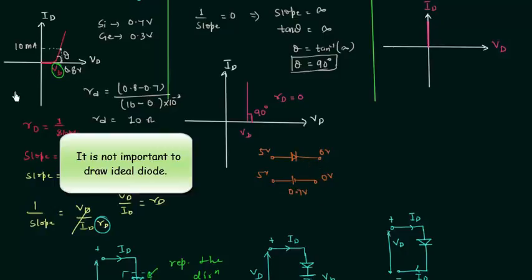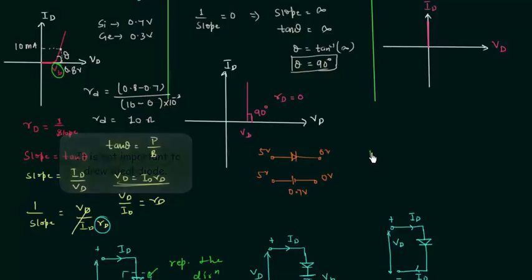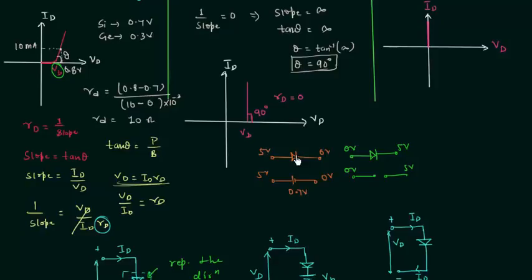And if the diode is reverse biased like this, this is 0 volts and this is 5 volts, P side is connected to the low potential and N side is connected to the high potential. So this is the reverse bias condition, and in case of reverse bias condition, there will be no current through the diode, so it will act as open circuit like this. These 2 points are very important, and by using them we can easily solve the numerical problems. In forward bias condition, you have to replace the diode by its barrier potential, and in reverse bias condition it will act as open circuit.